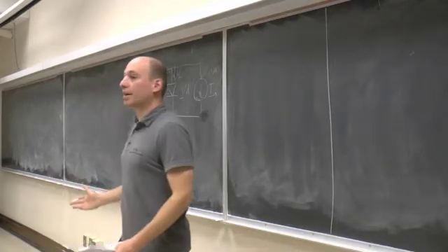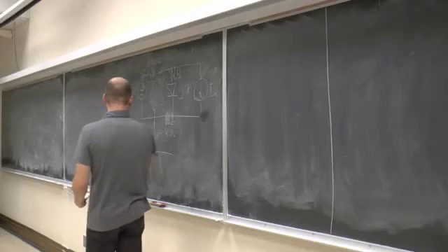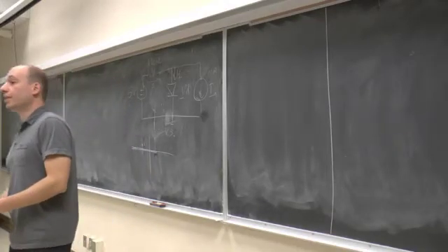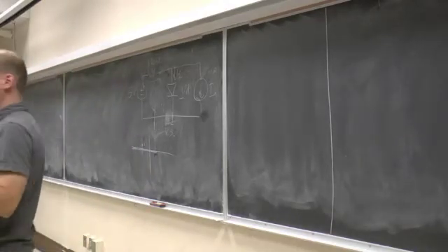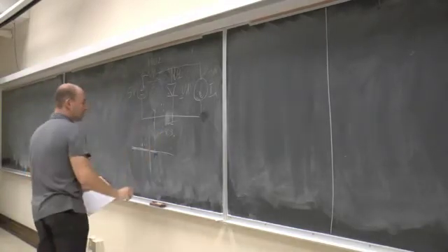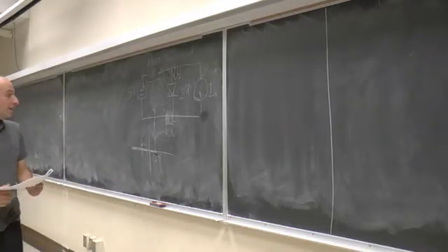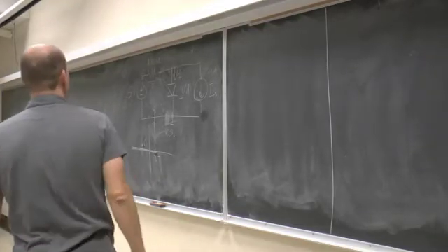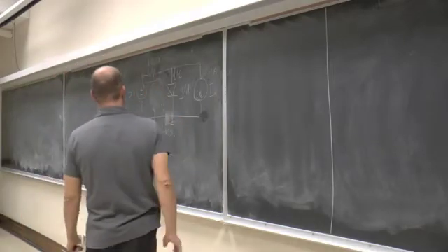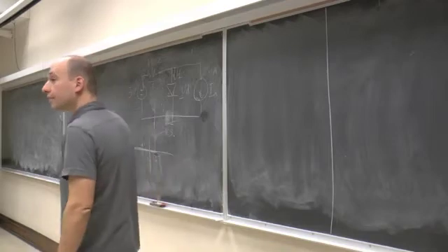If you go elsewhere and they talk about ideal diodes, that is true. It's going to be open circuit or short circuit, right? I emphasize those. But as far as lecture is concerned, we said we're focusing on the large signal model, where the turn on is 0.7 volts, right? Okay, so we can think for a second. Our first test is imagine this is an open circuit, right?